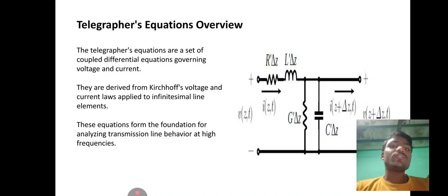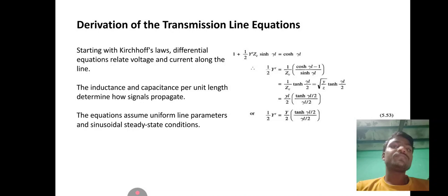Telegrapher's equations overview. The telegrapher's equations are a set of coupled differential equations governing voltage and current. They are derived from Kirchhoff's voltage and current laws applied to infinitesimal line elements. These equations form the foundation for analyzing transmission line behavior at high frequencies. See the diagram and equations.